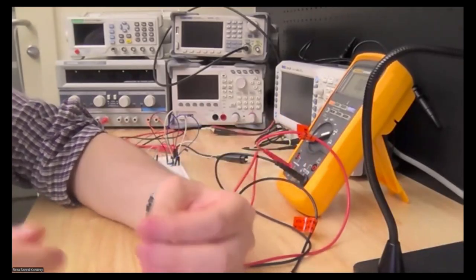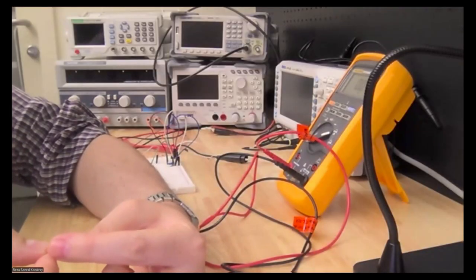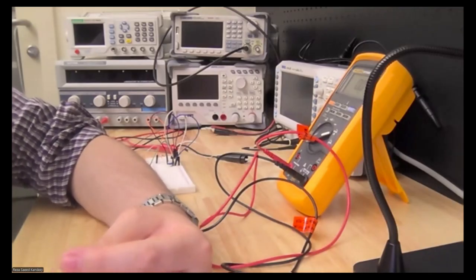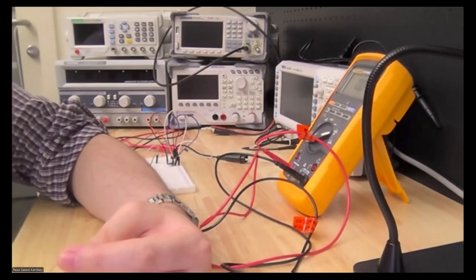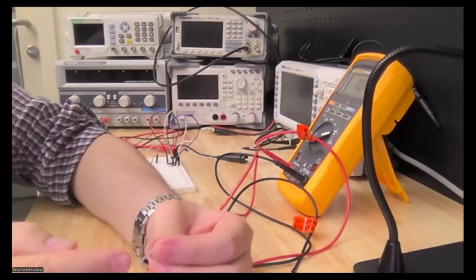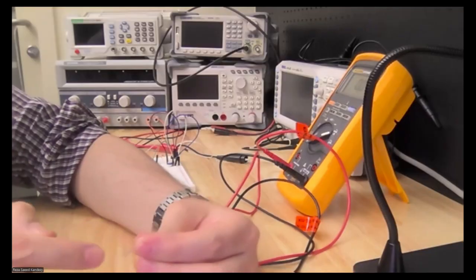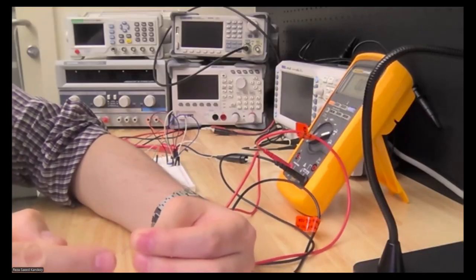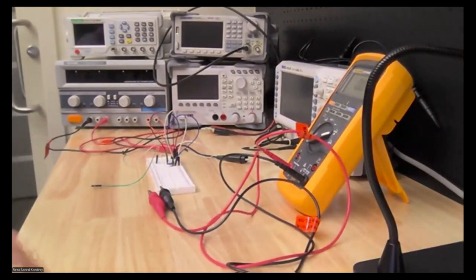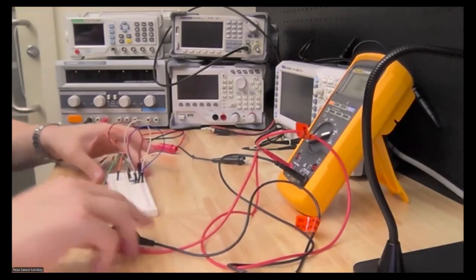Okay, now if you have the model P2N2222A, which is the other type of the BJT, the collector and emitter replace places. They change their place with each other. So in this model that we use, facing the flat surface, the left one is the emitter, the right one is the collector, and the middle one is the base. Now, let's move on to our circuit.